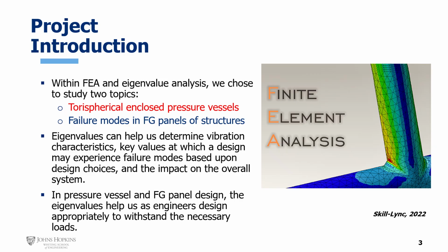So for the FG panels, or functionally graded panels, we looked at a study done by a few different people, referenced at the end. You can see the authors in the study itself, and it really focuses on the effect of porosity, material grades, internal cracks and defects, and how that affects natural frequencies and critical buckling loads of these panels.